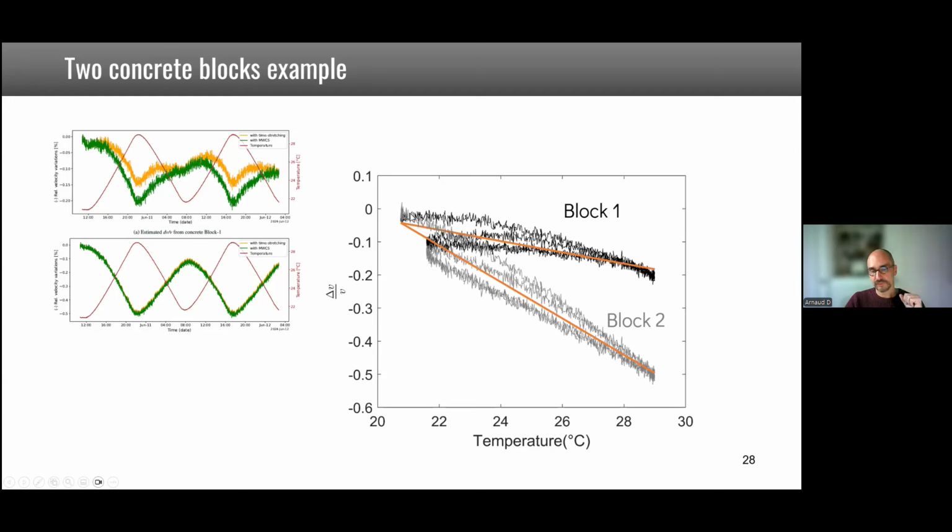But also you have some hysteresis. It's not really a straight line. And if you had been measuring only a few points, you could say, oh, yeah, this is noise on my data, and yeah, it's pretty linear. But actually, you see that it's not. There is hysteresis. And so if I do linear regression, I'll have quite some error between my prediction and my measured data. And so I will be a bit more blind to damage because I don't fit really well to the reality.